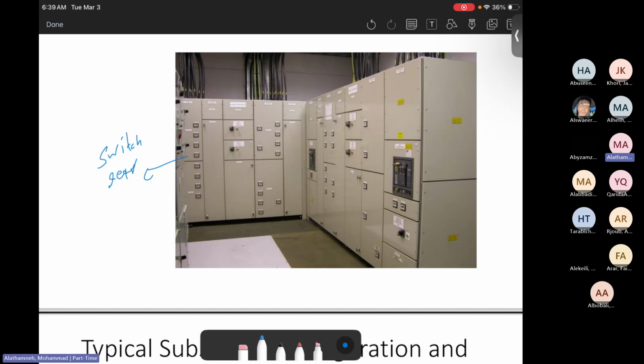Once we realize there's a fault, based on the CT and VT measurements, and again, by fault we mean there is an abnormal operating condition, then the relay will tell the circuit breaker to trip or not. There can be a fault like over voltage, overload, under voltage, or a mismatch in frequency, or over frequency relay, for several purposes. So the protection, the monitoring, the control, all of them will be inside the switchgear.